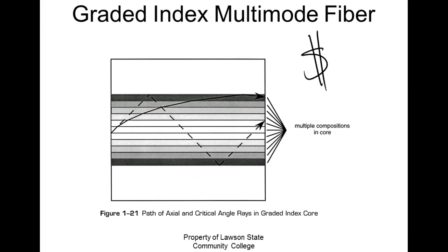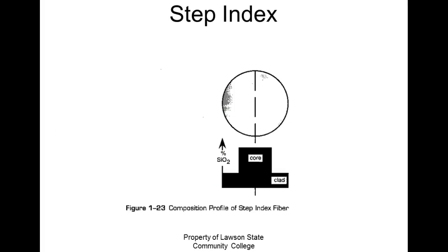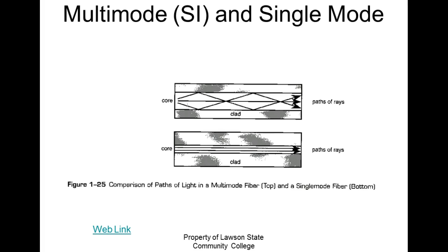So multi-mode, so we're using graded index fiber optic cable. But the splicing technique is basically the same for all these, and termination. So this is graded index, which is what we have. And it shows you, this is a nice picture right here. We went over the different single mode. The core is so small, it only allows one path to go. So we're looking around 9 microns on this thing, which is 1/6 the size of a 62.5 micron core, which is what we're dealing with.